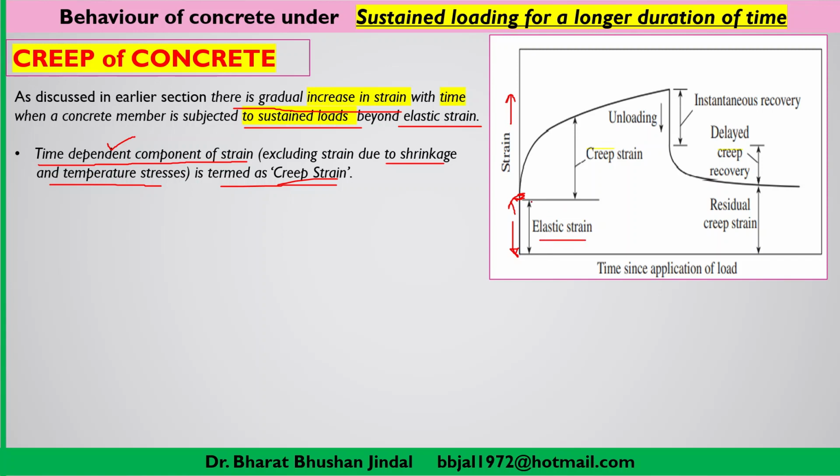Now you can see here beyond this particular point, the graph is just like a parabola, or you can say it is a curved shape. So this curve shape you will see here beyond the elastic strain, which we have already mentioned here. Beyond the elastic strain, the strain which you observe is known as creep strain, and that is due to the creep behavior. Now after that, the graph will be reaching somewhere here, and now let us suppose the load is removed, that means unloading takes place.